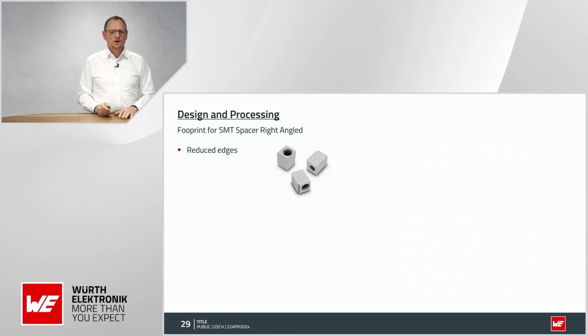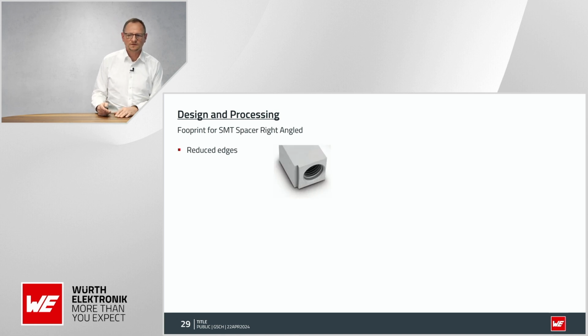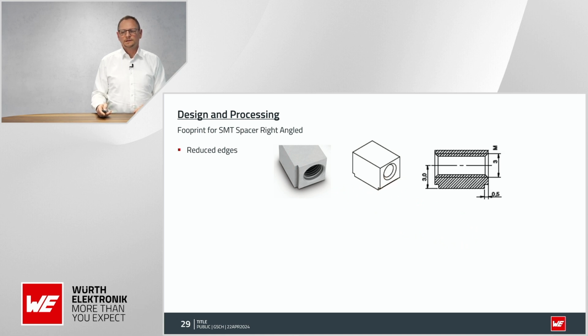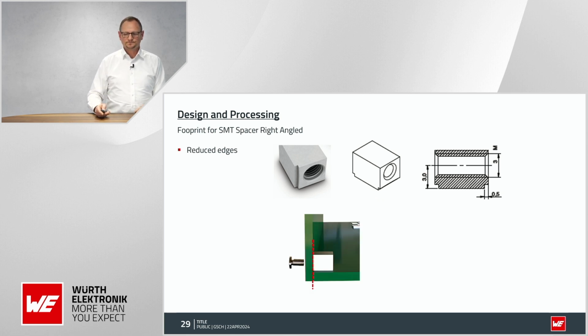So now let's have a look at the right angle types. We look at the footprints of the spacers. Of course, we have here these reduced edges. It's this gap here that I want to explain the intention for. This one is on the side, so this is the solder side, and now this is the correct position, and we have that edge over here. So this is like the drawing, and we want to achieve a clear right angle, and